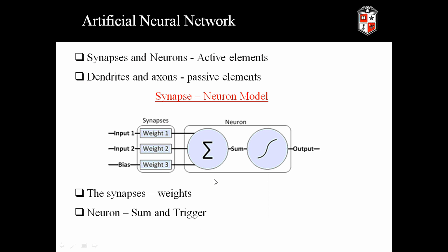One more important property of the brain is that it won't give the same weightage to different information. That means it provides different weightage for different information. How are we going to provide different weightage in our present hardware? It is very difficult to provide this weightage based on the information. As we can see, a memristor offers a different resistance for a different input voltage. That means it is offering different weightage for a different input.